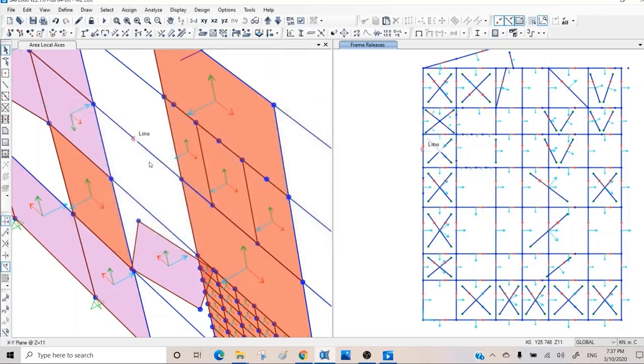And sometimes even axial load needs to be released. For example, you have a wall post at the end of the element with a slotted joint on top, so you don't want to transfer any load of the beam or frame to the wall post, so you can release even axial. The other thing, the last one I want to share, is when you have a moment resisting frame, you can define the end offset.